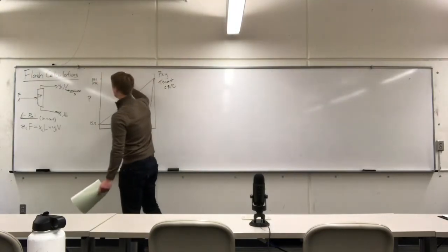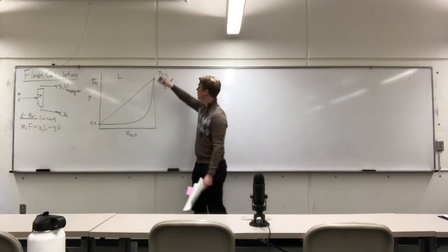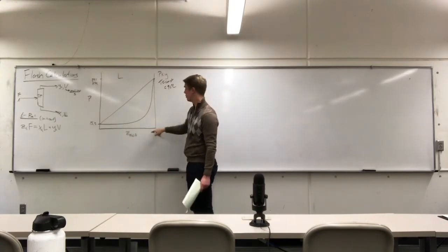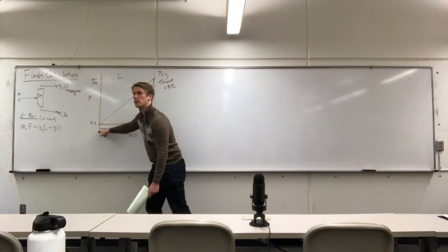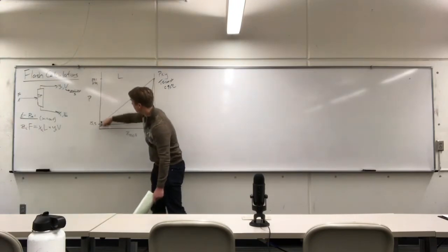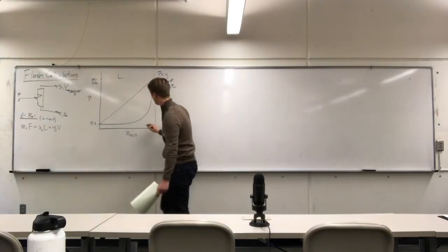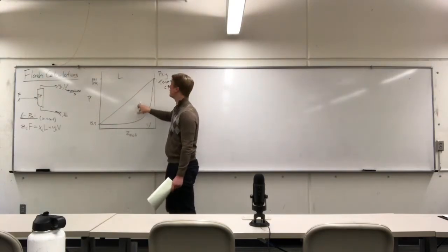Liquid. High pressure at a fixed temperature will condense us into the liquid phase. When I lower the pressure, the more volatile species will start to boil first, which is the methanol, which is 100% methanol over here. This is 100% pentanol down here. It takes a significantly lower pressure to boil pentanol. So that means down here we have our vapor, and here we have our two-phase region.